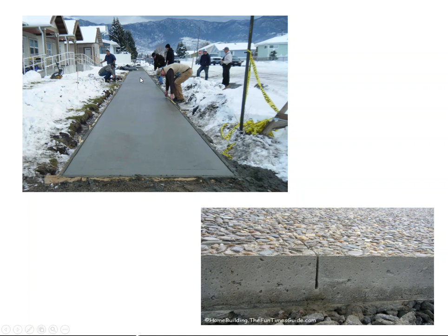And this upper picture, this is that same sidewalk we were pouring as for the class project, and you can see here Jim is laying out every 5 or 6 feet locations to perform not the saw cuts, where actually this is still a moist plastic phase, so we're just going to lay in an edge and create a seam without needing to saw cut a final product.